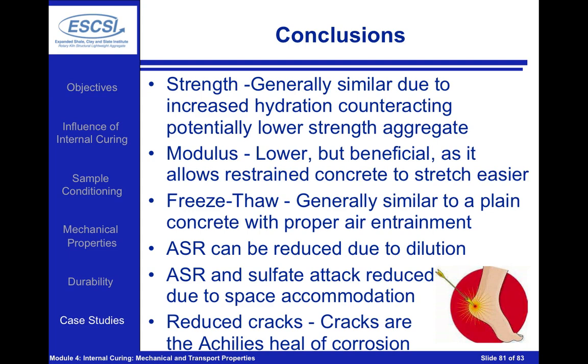So in general, we're getting a similar strength because we're increasing hydration. We're getting a slightly lower elastic modulus, and you may say, well, that doesn't sound like it's good, but a lower modulus is beneficial because it essentially makes the concrete easier to stretch, if we think about it in that way. So when concrete is restrained, we're getting a lower buildup of stresses in the system, which is going to make it less likely to crack. Lower modulus also means we're going to have lower microcracking taking place in the system.